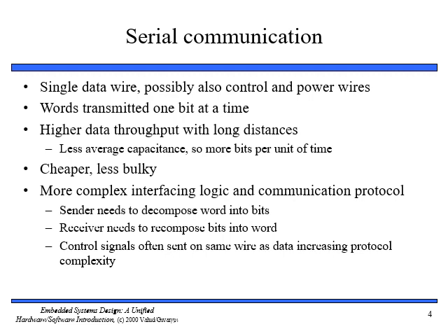Another common synchronization technique is to use an additional wire for clocking purposes. Here the transmitter and receiver devices use this clock line to determine when to send or sample the data.